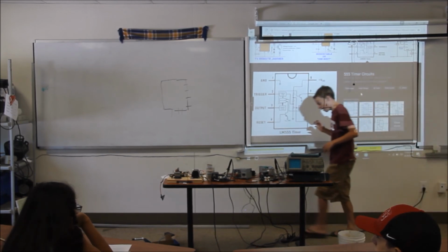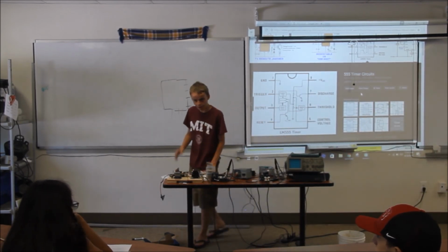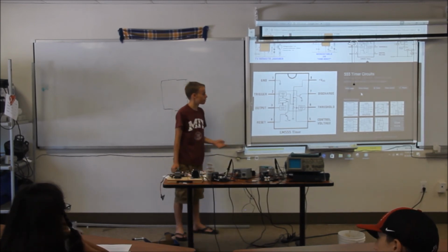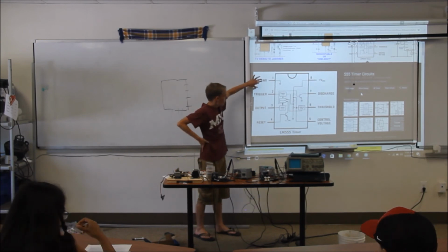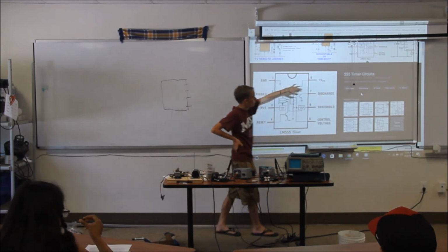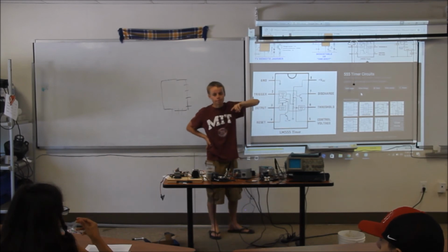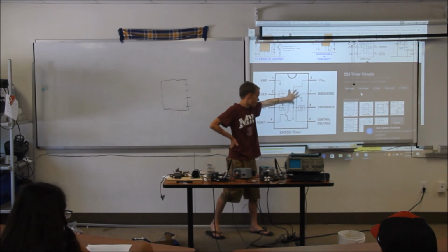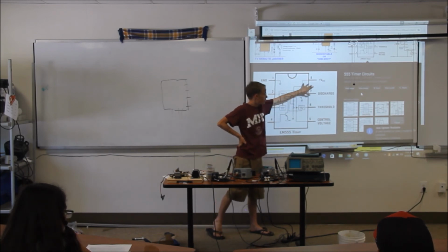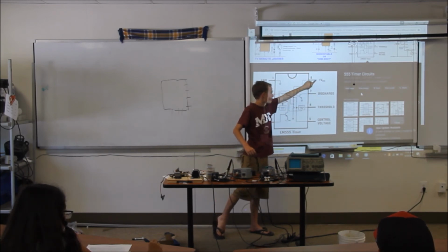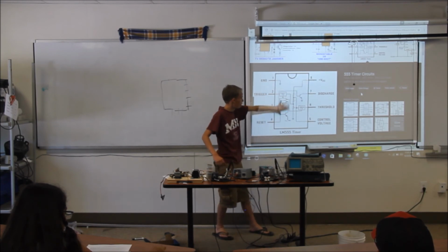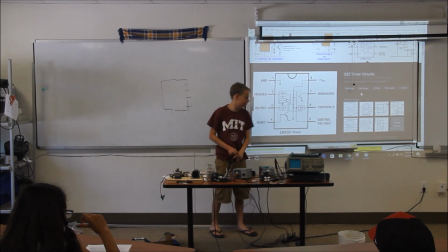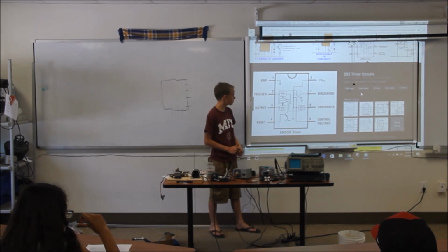The reason I'm teaching 555 timers right now is because I think they're an important part of electronics, because they can be used for a lot of things. So here we have ground, we have VCC. That means those are the places where you put power, because to make all the circuits inside here work, the 555 timer circuit is going to need to be powered by current flowing from positive through the circuit and back to ground. Alright. So you connect that to a battery, to your power supply, to anything else you want to do.